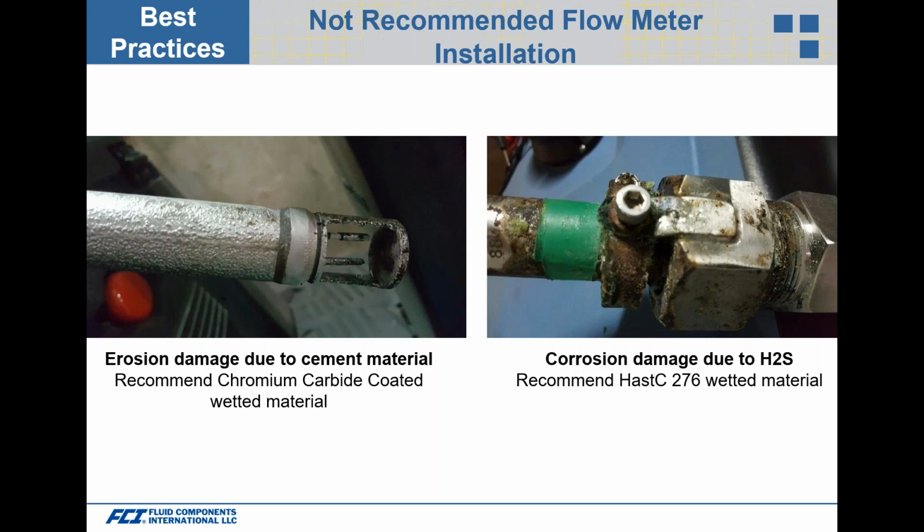And then corrosion damage. This one's showing H2S, hydrogen sulfide. Recommended Hastelloy C wetted material. So it becomes critical also that you understand the process gas and what flow element material is compatible with it.